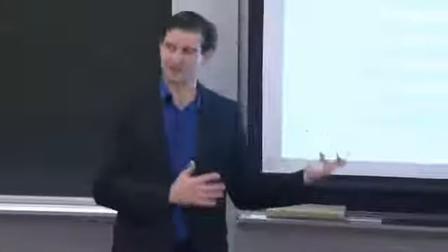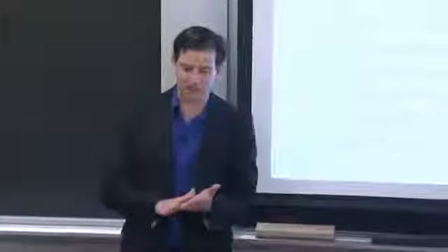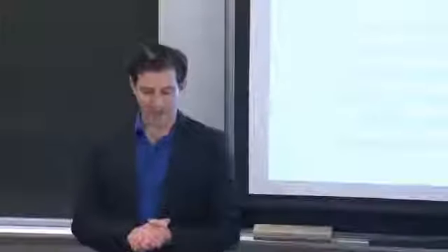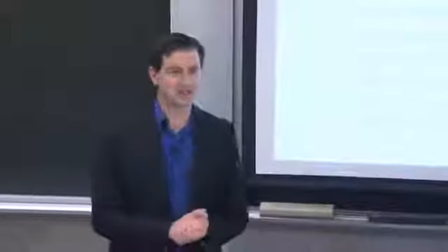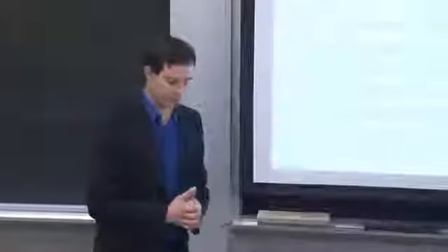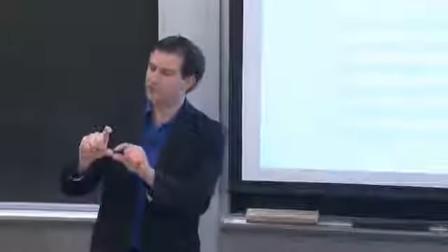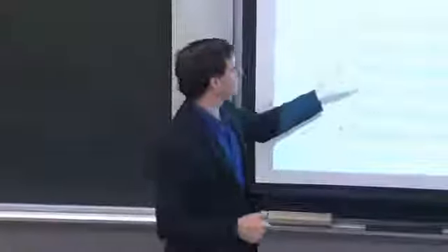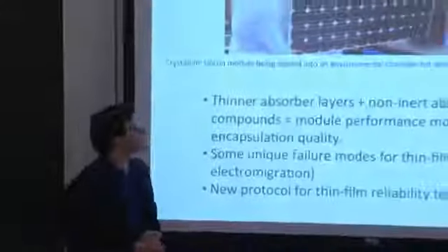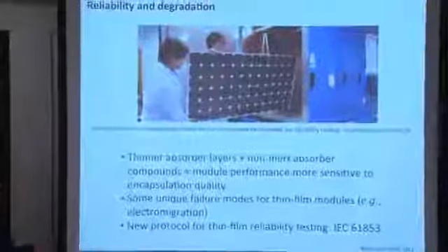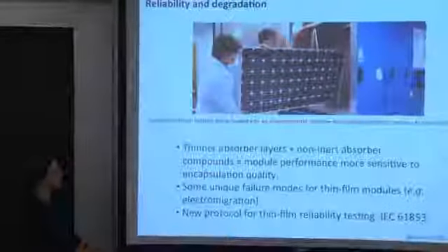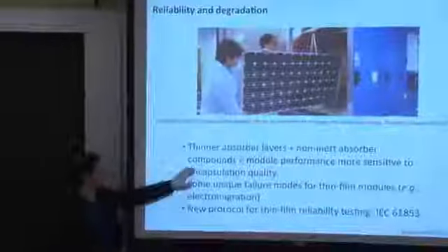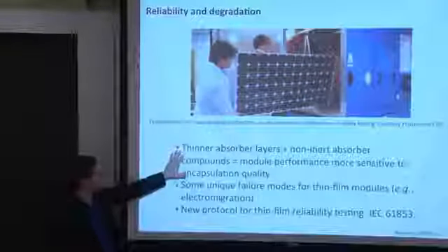But now if you take a fairly reactive thin film material that might react with air or might react with water, and it's so thin that these rusting modes, these reaction or weathering modes, can really impact a large fraction of the thickness of your device, you become a lot more sensitive to accelerated degradation. You become a lot more sensitive to the elements, and this includes both oxygen and water. So if the ambient is able to penetrate through the encapsulant and get to the active absorber material, you may have accelerated degradation of module performance as a result.